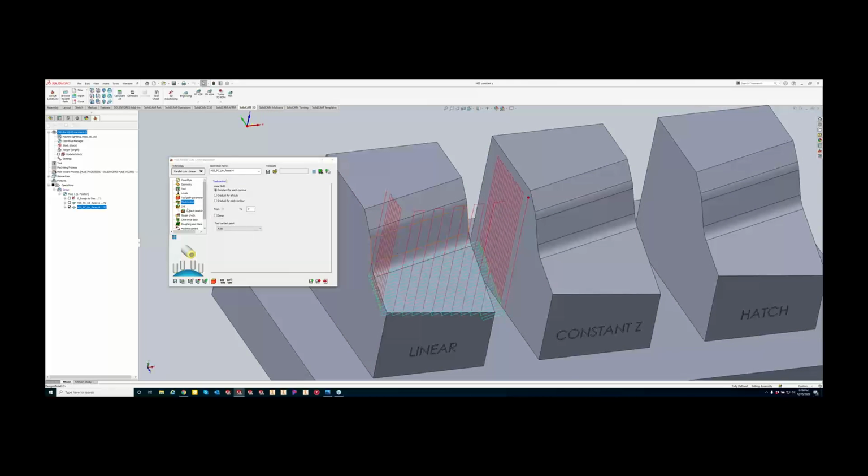Now, in our link page, we're going to make this tool path look a whole lot prettier. So we're wasting a ton of time going up and down and moving back and across, up and down. So what we can do to clean up that is go to our links tab. So right now, if we have any gap in our surface, and I'll show this on the next part, we can fill that gap in just by telling it to go over that surface without having to do a surface fill. Like I said, I'll show you that on the next part here.